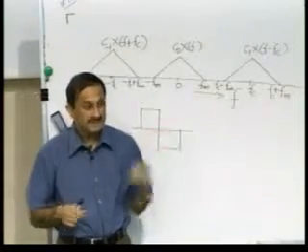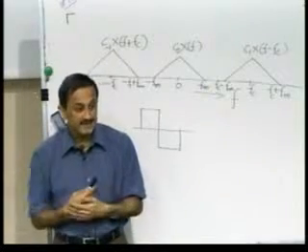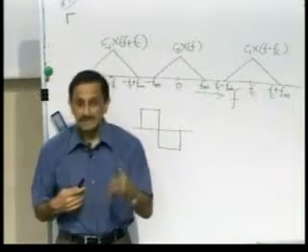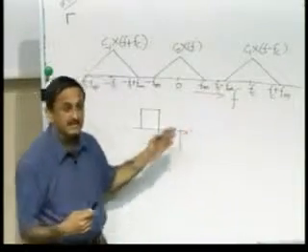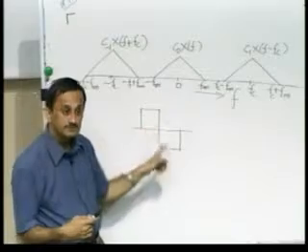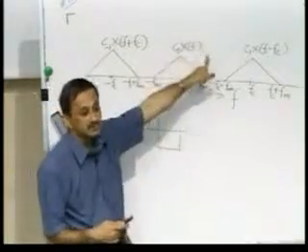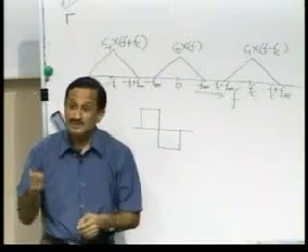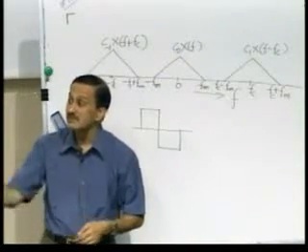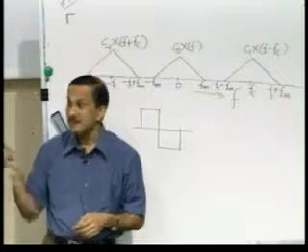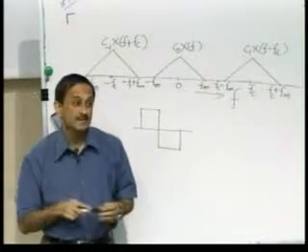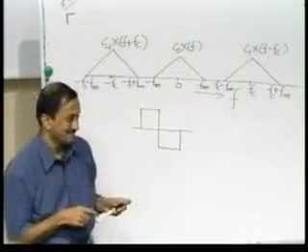So, if you do something like that here, but at a much higher rate, right, at a rate of Fc, then you could effectively achieve multiplication of the original periodic pattern, which amounts in the spectral domain to creating a false replica spectrum, and you are retaining a false replica and throwing away the true one. That's why we are calling it aliasing, and we are doing that to advantage to create a modulator.